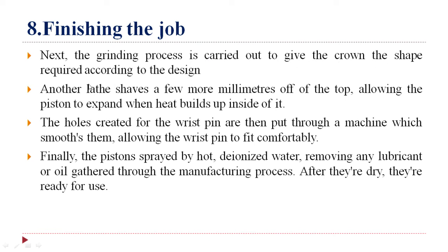Another lathe shaves a few more millimeters off the top, allowing the piston to expand when heat builds up inside of it. The holes created for the wrist pins are then put through a machine which smooths them, allowing the wrist pin to fit comfortably. Finally, the piston is sprayed by hot deionized water, removing any lubricant or oil gathered through the manufacturing process. After they are dry, they are ready to use.